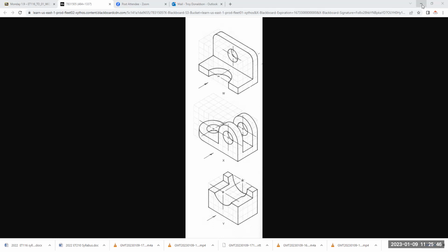You can just TR and then draw that line through things you want removed. And if I keep the pick button pushed, it'll show you what it's going to do. If you hit escape, or if you actually let up on your finger, it does it. But you always have the undo button here to bring it back.